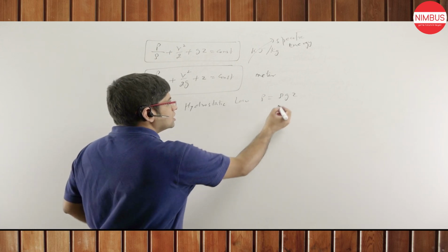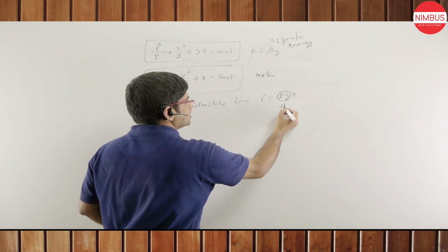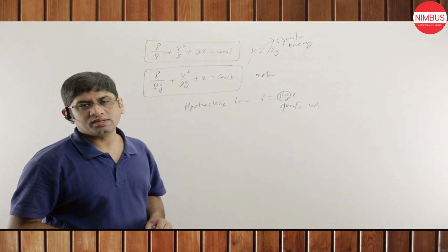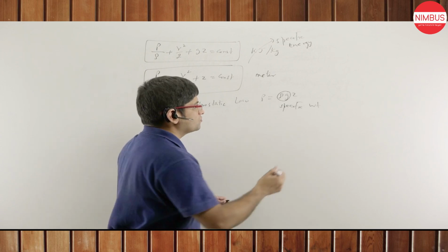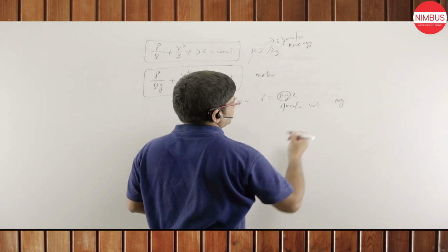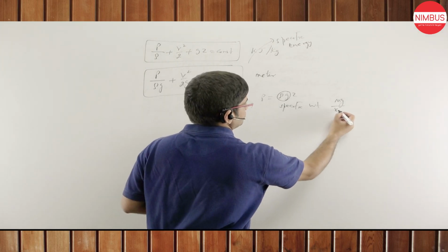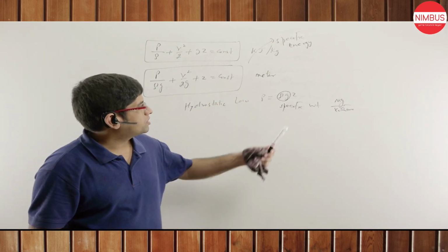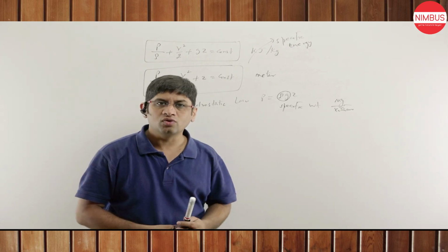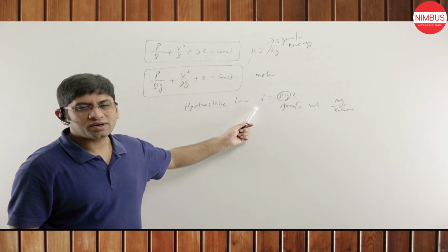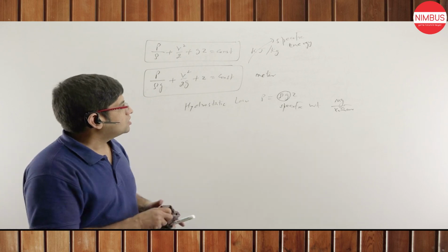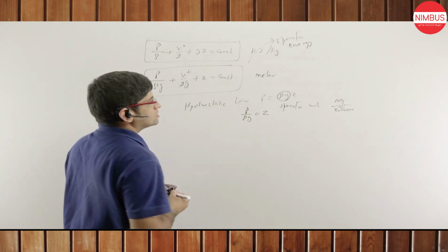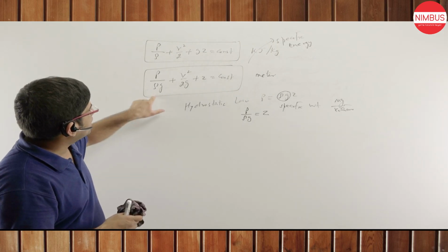And what is rho G? Sir, rho G is the specific weight of that fluid. That means weight per unit volume. If the weight is mg, and I divide the weight by volume, mg by volume, it becomes rho G. That becomes the specific weight of the fluid. So hydrostatic pressure at any depth Z is rho G Z. Now can you divide P by rho G? What do you get? P by rho G is equal to Z, and that is the reason P by rho G has the unit of Z.